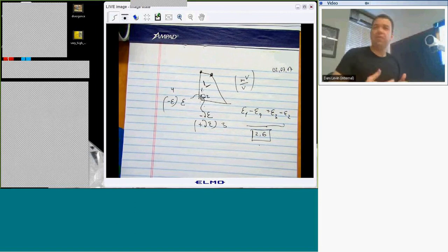If you don't know what your instrument is supposed to give you, this is all a guess game. Okay, so yeah, you certainly want to do the analysis first, because that gives you some guidance when you start making the measurements. Also, each of these instrumentation arrangements is designed to emphasize one mode or another, but each of those strain gauges will presumably give you a response at every resonant frequency.